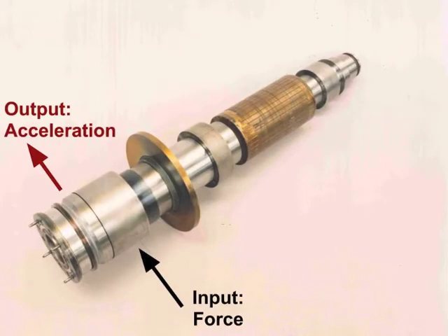Now we'll look at another frequency response. And here, the output location is the same as before, but the input location has moved. I now have my input force at the front bearing, not the center bearing. And so, the transfer function will be different. It will be different because the zeros will be different. The poles are unchanged by where the input and output are located on my structure. Let's see how the frequency response of the system has changed because of the different zeros in the transfer function.